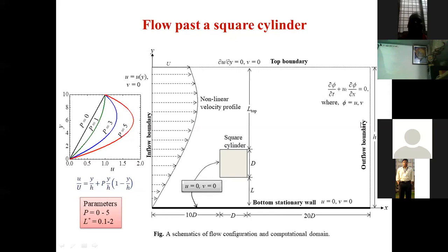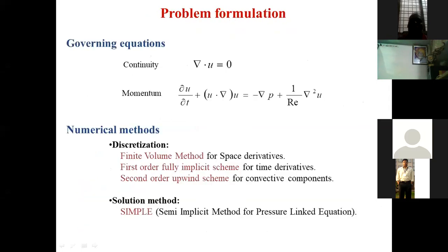But because we are taking the help of the computer and solving this numerically, we have to put these boundary conditions and tell the computer to cut at this boundary. So suppose this is my whole computational domain. We solve these equations over this whole domain. So first step, we discretize this whole computational domain into small meshes. So this is the method. Here I have used the finite volume method to solve these governing equations.